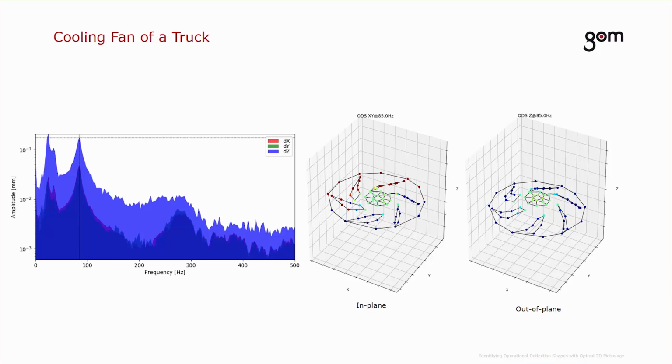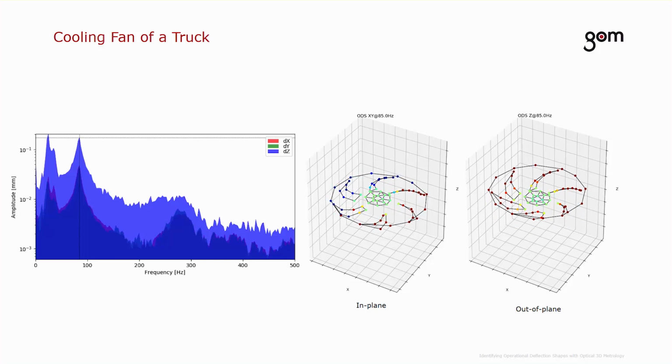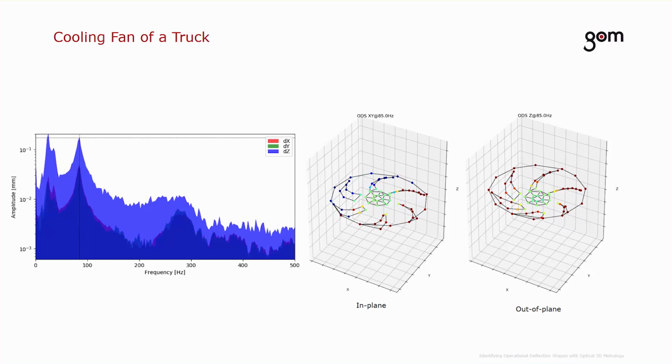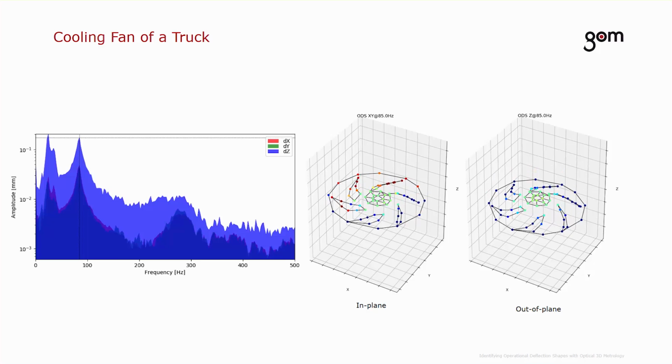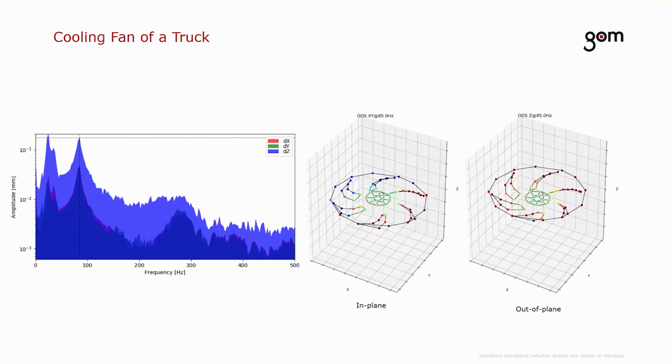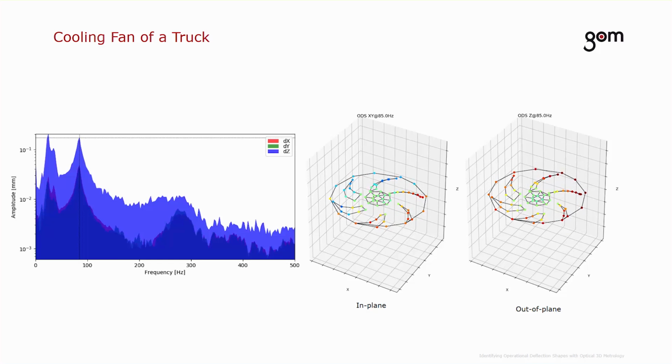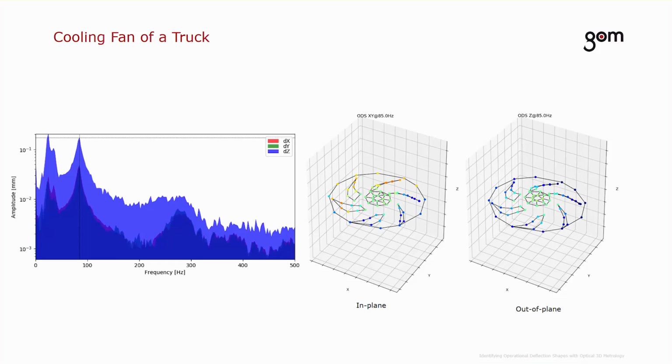So we accidentally, in the testing that we did with the operating fan, came close to the frequency to bring it into resonance. So here we can see the result coming from the hammer impact test, and this validates basically what we measured also in the operating state of this component.